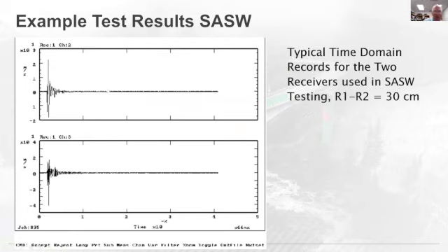These are time voltage plots. The big spike of the energy, this is time and this is a voltage, or it can be calibrated to be the response of your transducer. But the big spike is the surface wave energy, because when you hit the concrete, about 2/3 of the energy you generate is surface waves. 26% is shear wave energy, and 7% is literally a compression wave, the impact echo type energy that we use compression waves for, or ultrasonic pulse velocity, as we'll talk a bit too. So you can see the bottom one, it's slightly later in time when the big surface wave pulse goes past.